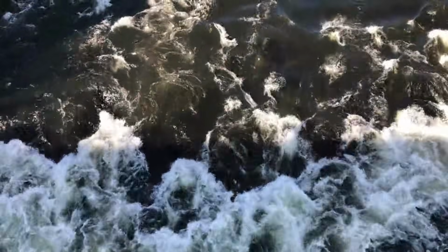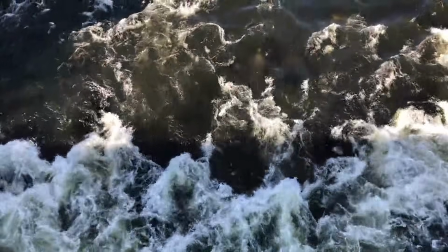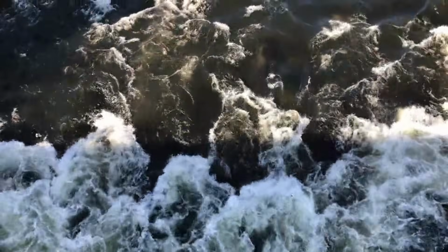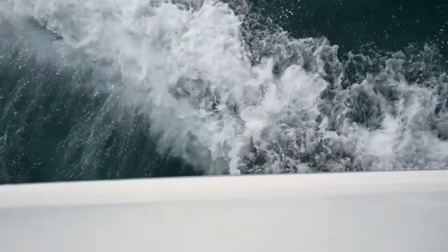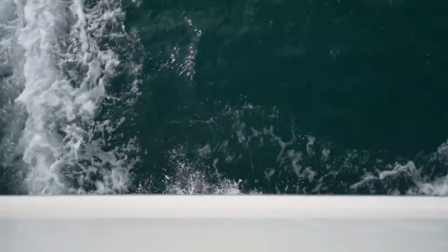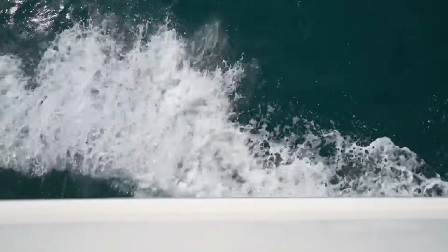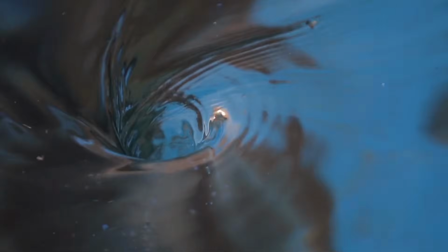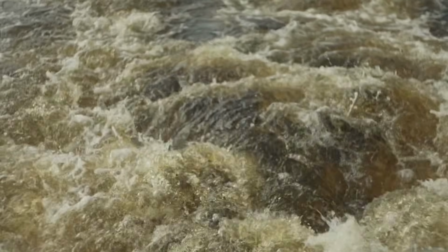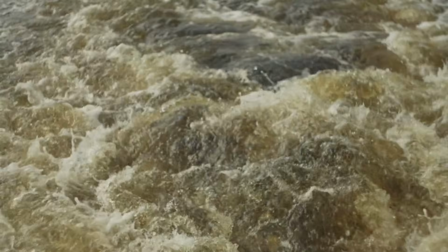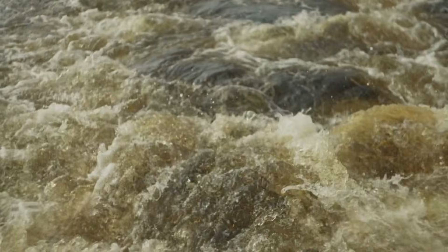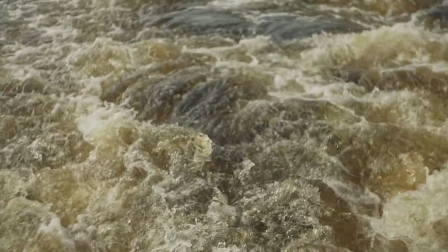In a standard laboratory flume, water flows in neat, predictable layers. In a dam break, the Reynolds number, which measures the ratio of inertial forces to viscous forces, skyrockets into the millions. This means the flow is highly turbulent, characterized by eddies and vortices that consume energy in a non-linear fashion. This turbulence is actually what saves some structures. The energy spent creating these microscopic swirls is energy stolen from the forward momentum of the wave.